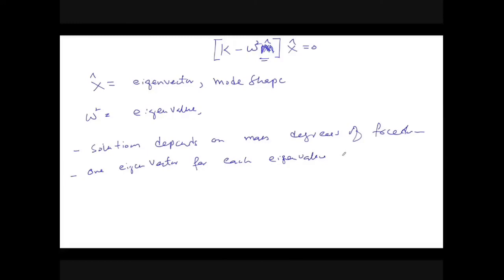Every solution will give you a mode shape, and it will give you the frequency of vibration of that mode shape. And each mode shape is unique and has only one corresponding frequency or period of vibration.